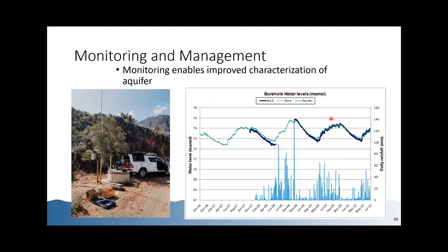There's other interesting aspects that one can pull from groundwater monitoring data. And in this graphic, we've got two boreholes located a few hundred meters apart. But when we plot their water levels, we see that they are almost identical. And these boreholes are both located in the same aquifer, and you can see it from their signature. And where you've got multiple boreholes that are abstracting from the same aquifer, as the graph that Kes showed, you can then start to see to what degree these boreholes impact on each other, which is again critical to the management of your borehole or your boreholes.